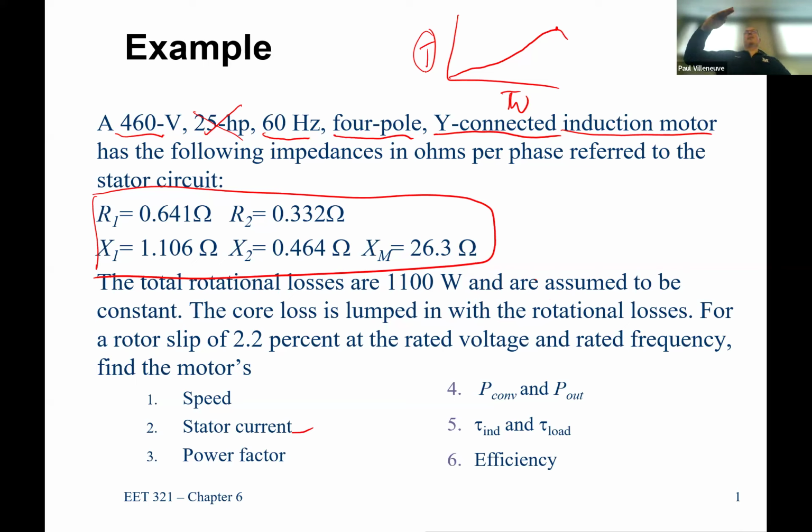So if your pump is here and your motor is here, they better be aligned pretty perfectly. Because what happens if the motor is this way? Now, even off by a degree, you actually can get the torque, and you can actually get tension. You can get things breaking. They don't always work. And so one of the things that mechanical engineers have to deal with is a term called a shim. You know what a shim is?